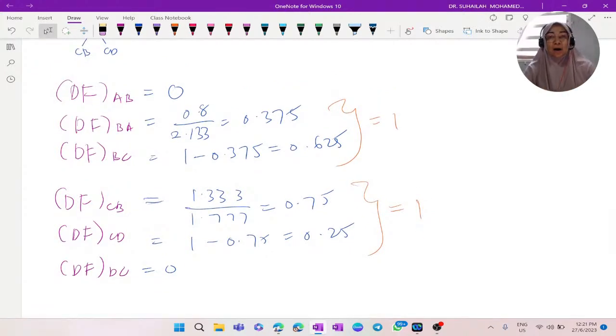So this is how to understand stiffness, which includes member stiffness and joint stiffness, and stiffness depends on three factors: the modulus of elasticity, E, which is under material properties in the software; the moment of inertia, I, which is under section properties; and the length of the member.